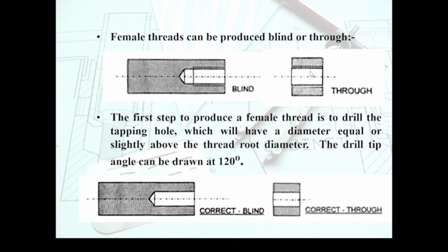There are a few things that you need to be bearing in mind in terms of sectioning through a threaded shaft or a threaded hole, and the illustrations are provided here. Once again, the threads are not literally drawn onto the drawing paper. We generally use a thin continuous line to indicate the part of the hole. So this is actually a female body, and the female threads are represented on here. Really, every time we create a technical drawing representing that, we will always have a 120-degree angle inflicted by the drill at the end of this, really.